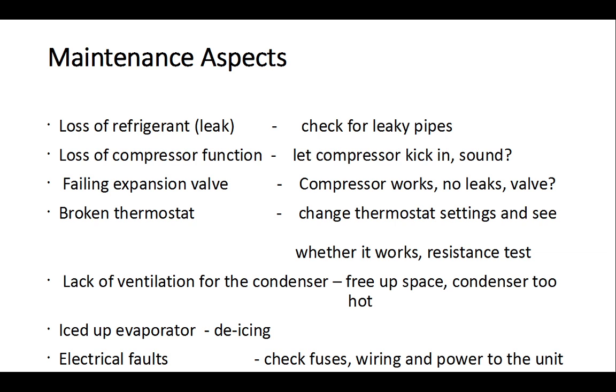By the way, it's also a little piece of advice for home if your electricity bill is fairly high. Check your fridge and see whether it's all iced up. If it's iced up, knock all the ice out, de-ice it, and it'll be okay.